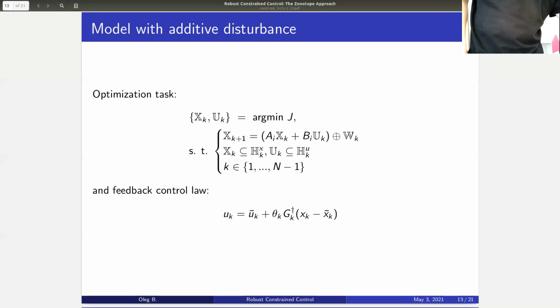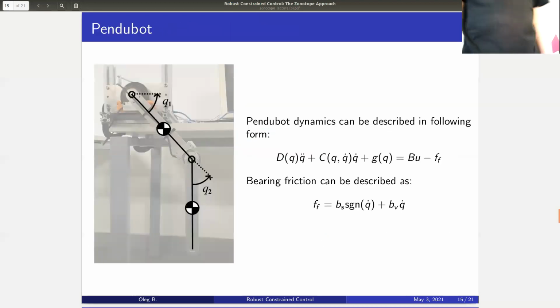If you don't mind, I think this discussion gets to an interesting point in control. There are 2 styles, historically at least, to approach transient processes in control systems. One of them is to say, okay, we have overshoot, we have the time of the transient process, or the settling time, etc. Those are very industry-driven ways of thinking. You would say, how long is my motor going to take before it settles, or how much does it overshoot? And that is something people used a lot when they tune controllers, especially PIDs.